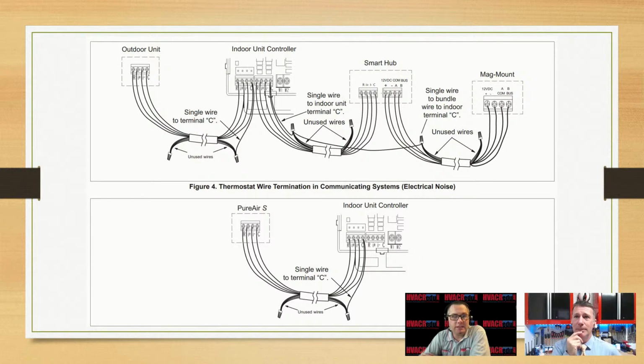So give me an idea. This typically is your 18 whatever, control wire. Yep, 18/7, 18/8, whatever it might be. Your typical thermostat wire, non-stranded. It's better to use stranded, of course, I prefer stranded. Right? But nonetheless, I've had very little problems with solid core wire before, but stranded's always better. Exactly.